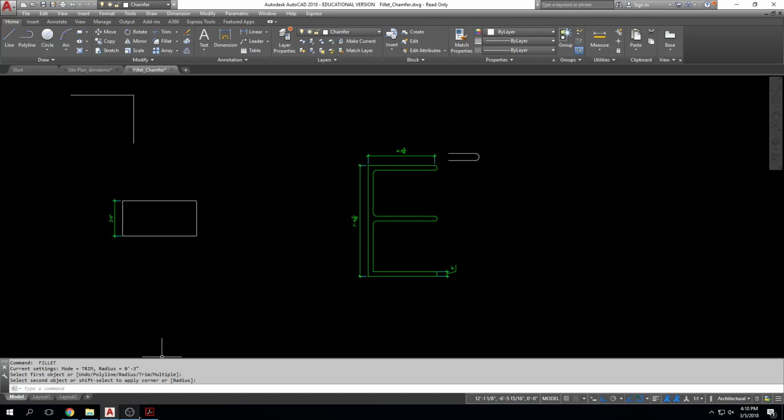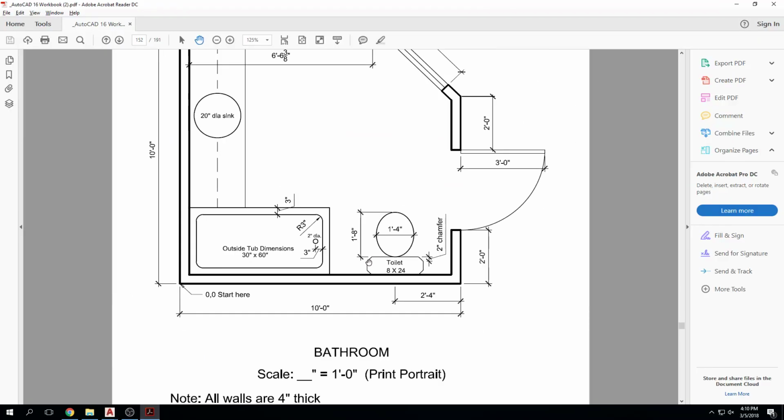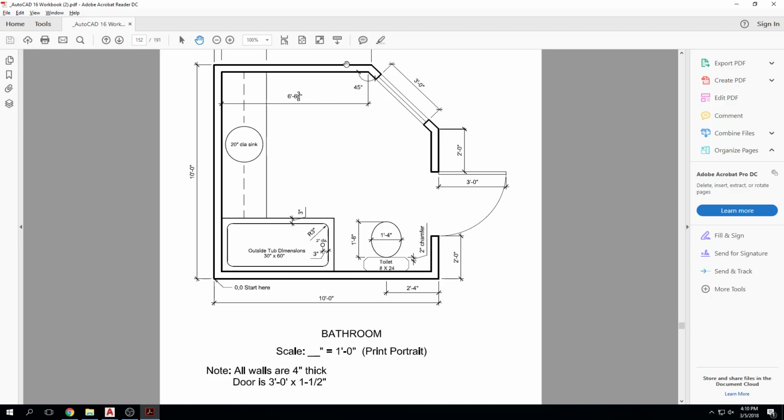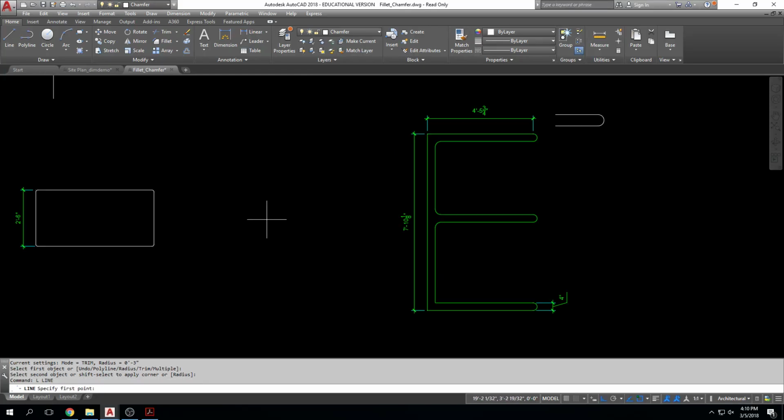In the bathroom exercise, in this exercise, if you create the outer boundary of this using lines, and then you offset them in, right? And you've maybe found this with other assignments, when you offset lines in, they don't always come in with these nice squared off corners, right? They come in and they have corners that don't quite meet. They look somewhat like that, right? And up until this point, you didn't really know what to do with lines like that because we didn't have any way to clean them up, okay? Fillet is gonna be that first tool that will allow you to clean those up.